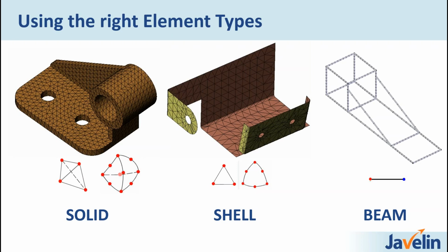And in an ideal world, we'd use solids for everything. They're nice, they're easy to use, the meshers work very quickly, the contact works very well. The issue comes with thin-walled structures. When you get into things like sheet metal or beam elements, pipes, things like that, to get enough elements through the wall thickness to accurately capture the stress component out of that, you're going to need lots of very, very, very small elements, and that can be an issue.